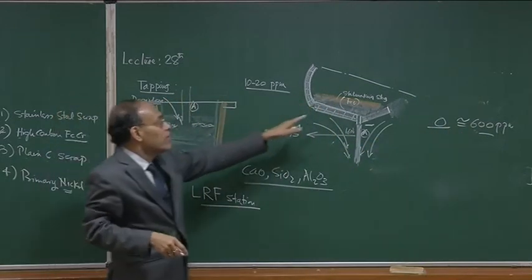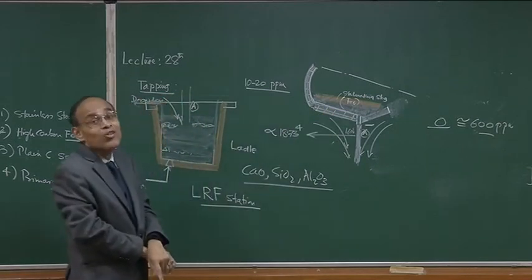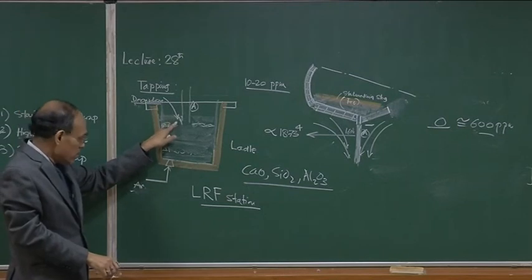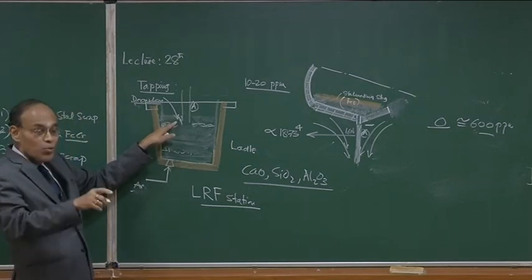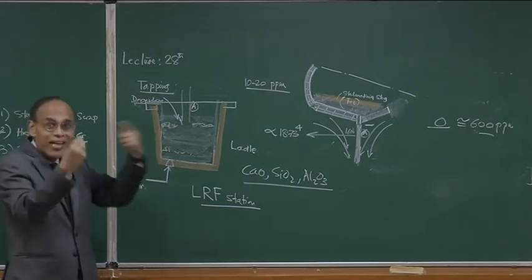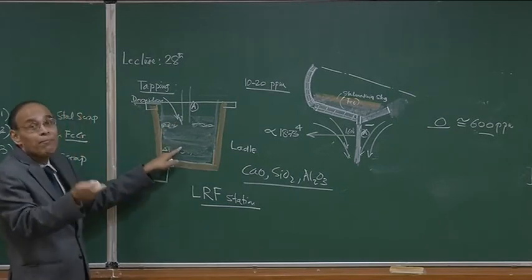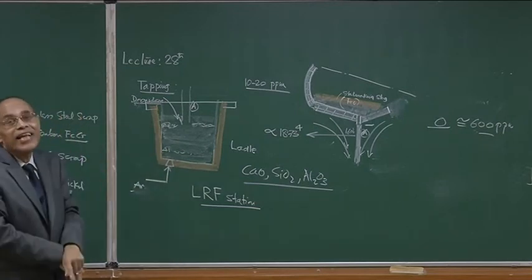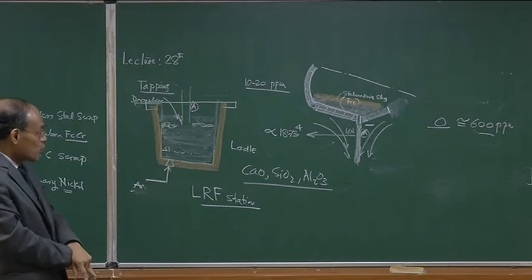When you have carryover slag, this is called the carryover slag. The presence of carryover slag in the ladle is detrimental, for economic reasons, because the deoxidizer will be eaten up by the slag rather than dissolving into the melt, but more importantly, as we will see later on, this will tend to make steel extremely dirty or full of oxide inclusions.